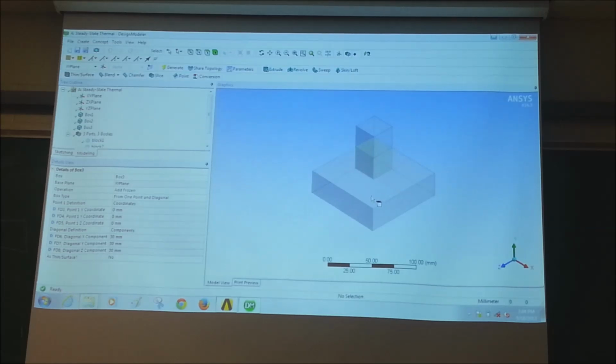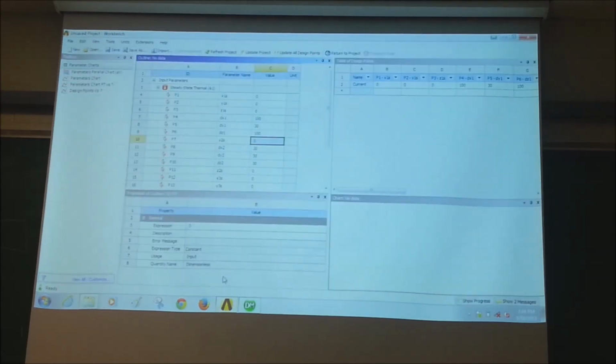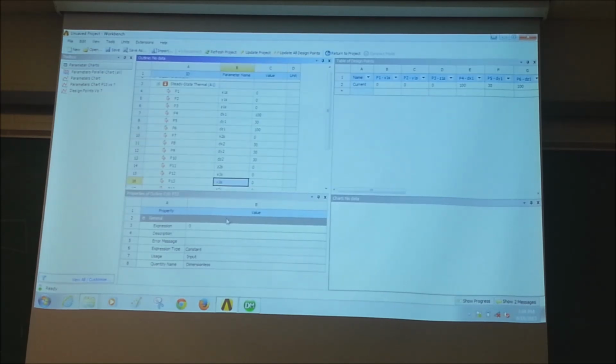So now you go up here, this is the beauty of parameterizing, right? Watch this now. This is really something. So now, which one do we want to fix? The starting point in the y direction, right? So we want Y3S. Y3S is a problem, right? So I'll go to Y3S, I click it, and then come to expression here.